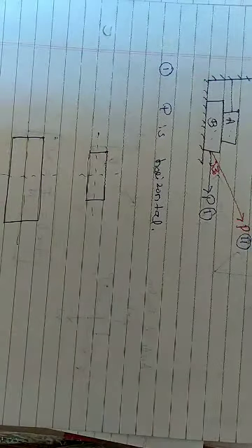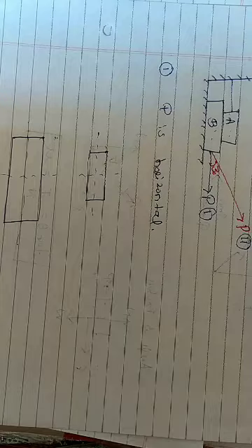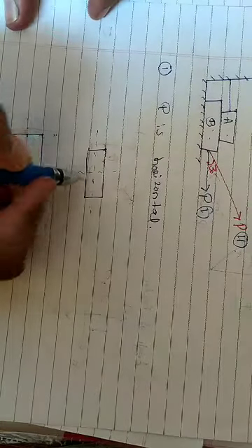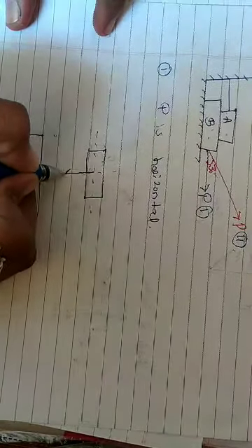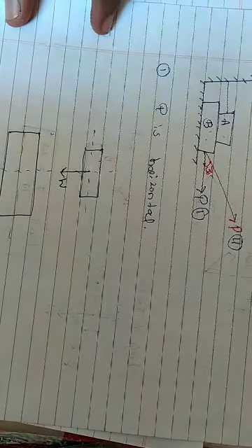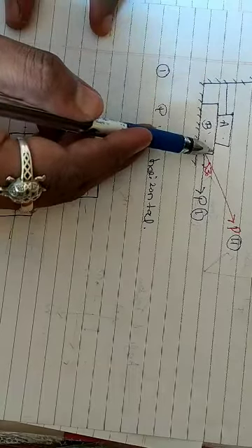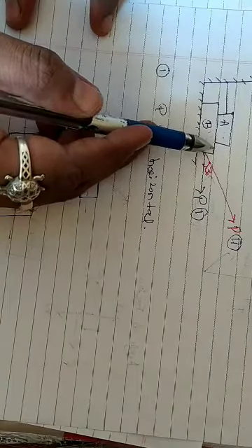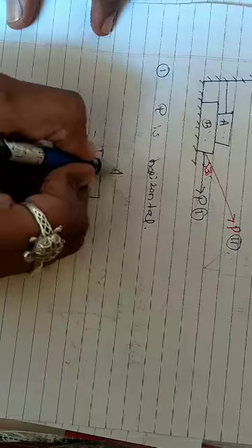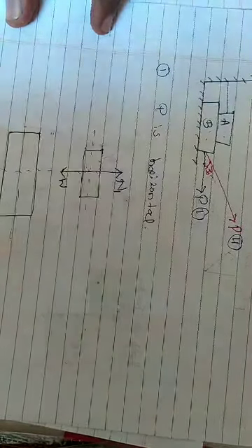In friction problems, when we are dealing with bodies connected to each other or a body resting over another body, we need to consider each body separately and then draw the free body diagram. When you consider block A, weight acts vertically downwards. This is W. There is a contact surface here which is perfectly horizontal, so we get a perfectly vertical normal reaction. We'll call this N1.